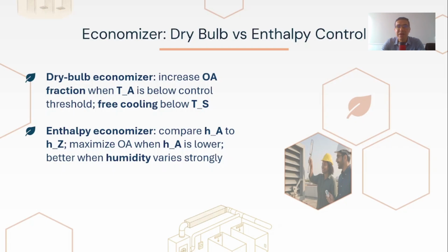So this is related to the question at the beginning of the video. Remember that you remove sensible and latent loads. So even if you have air that is slightly over the supply temperature, because it's dry, you can have lower latent loads to remove.